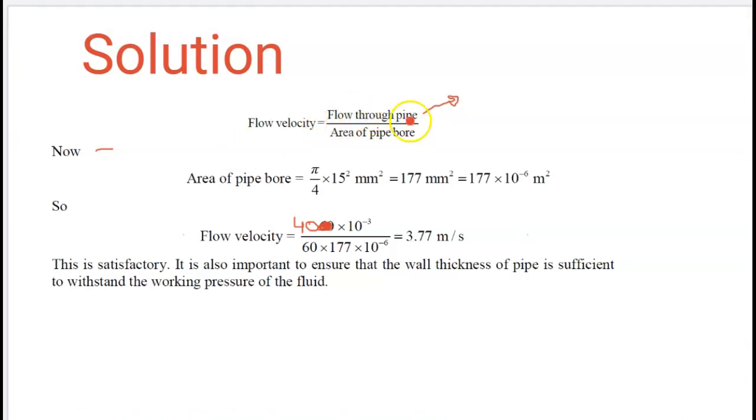So we have the flow through the pipe value, which was 40 times 10 to the minus 3 over 60. You can keep that value just to make sure you do not round off whatever answer we get. Let me just put the answer. That will give you the value 6.66, 6.6 recurring times 10 to the minus 4 meter cube per second.